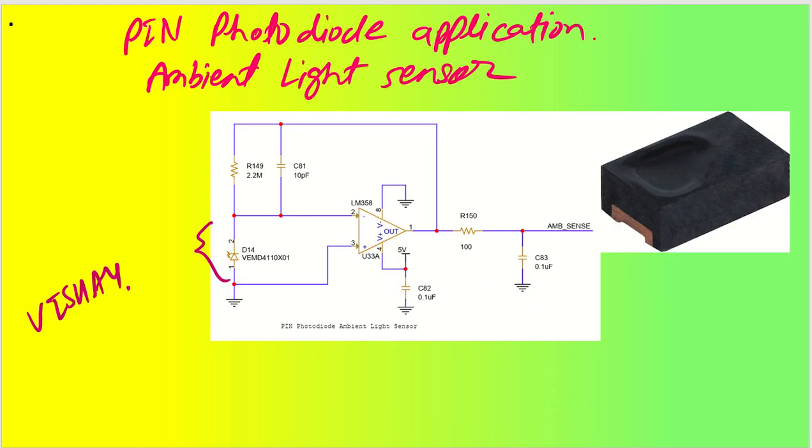As I was saying about the light sensor, this is the ambient light sensor. It is going to receive the light, and it is going to give you an output voltage based on that particular measurement. This will be connected to my ADC, and the ADC will give you the understanding of the amount of light in your environment. If the light is low, then based on this decision you can switch on the lights in your room or inside your car or everywhere. These are used in cinema theaters, home appliances, automotives, everywhere, for your ambient light sensor application.